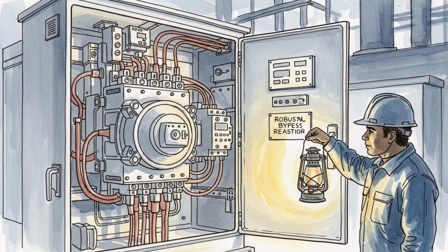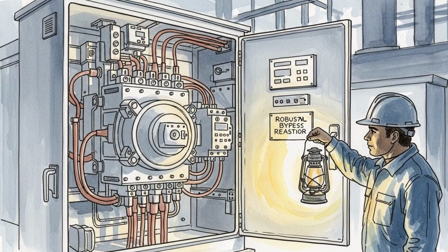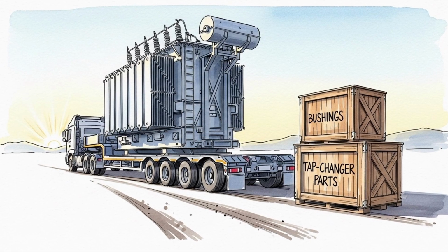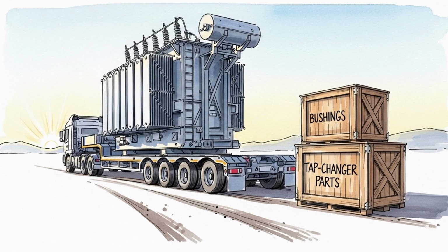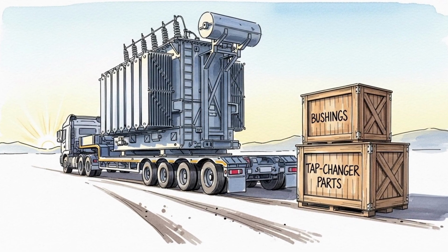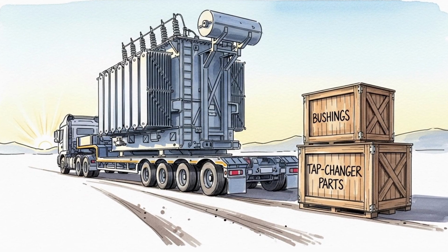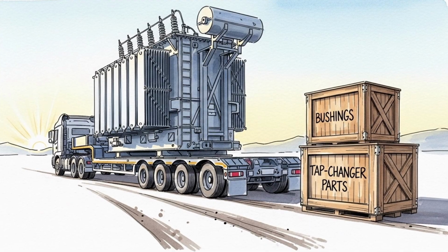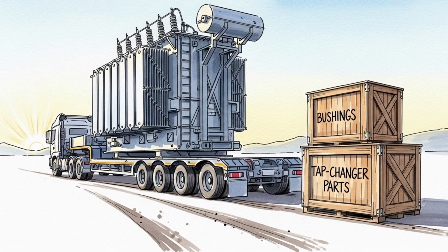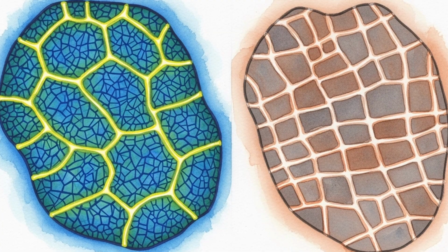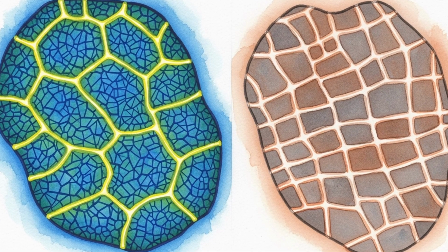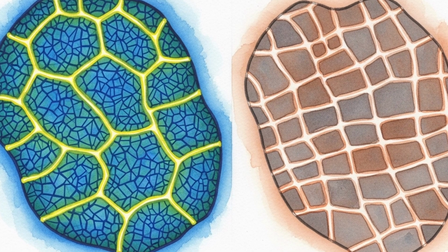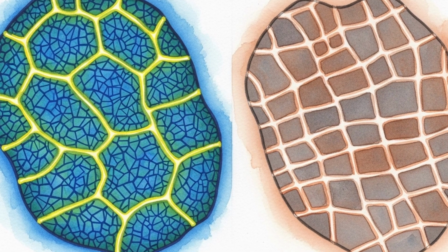Secondary effects follow from the primary saturation. Harmonics rise on the network. Relay measurements become less accurate. Capacitor banks and static VAR compensators see unusual loading. Operators must supply more reactive power to hold voltage. If reserves are not ready, undervoltage can spread. In extreme cases, windings or leads can overheat, which risks permanent damage to the transformer. Replacement of large transformers takes time, so prevention and controlled operation are preferred over run to failure.